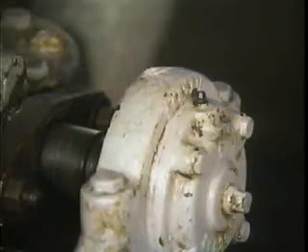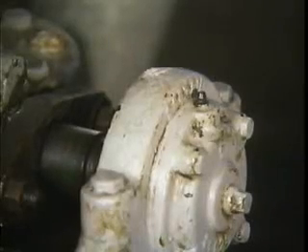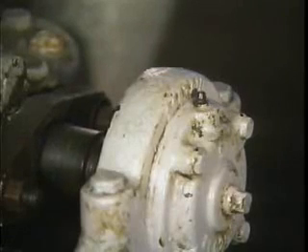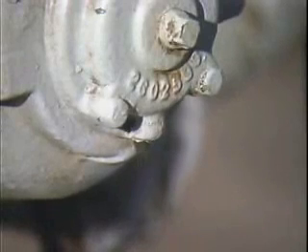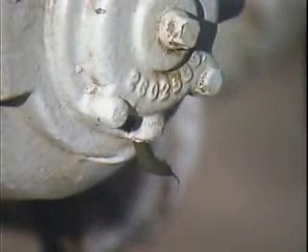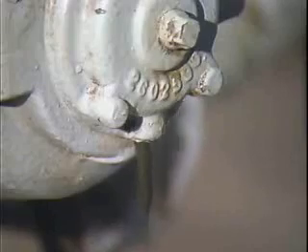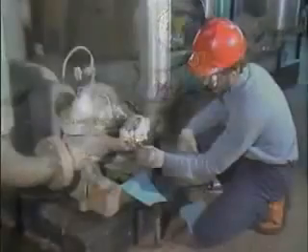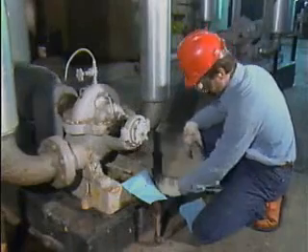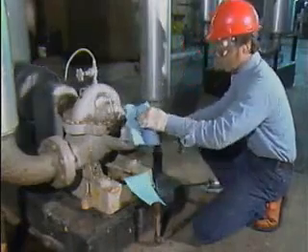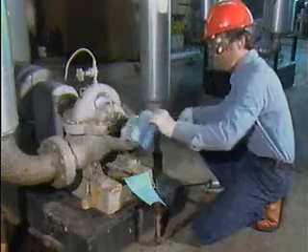Anti-friction bearings often have housings that retain grease and help keep out dirt. But a problem can occur if too much grease is put into the bearing, because there's no place for the excess grease to go. Consequently, a way for old grease to leave the bearing must be provided. In this example, the housing has a drain hole. To prepare to grease the bearing, remove the plug from the drain hole and wipe the grease fitting clean.